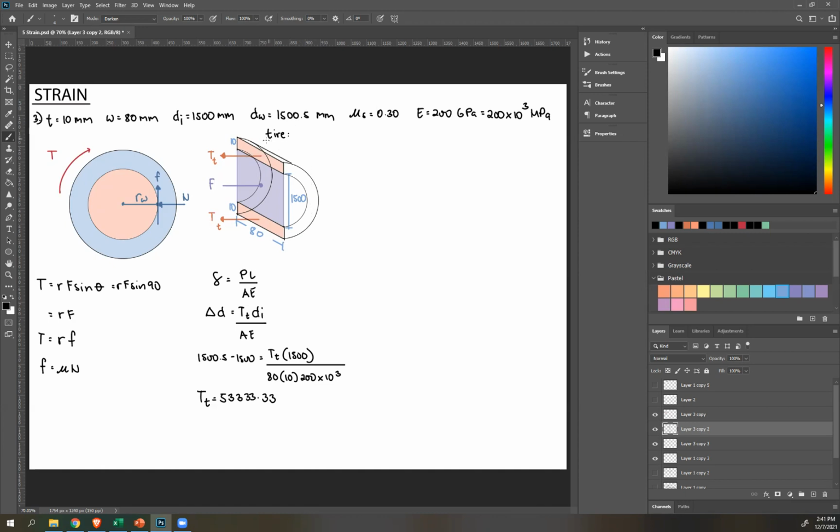I can use equilibrium equation here. Summation of forces equals 0, F to the right. Oh, this is Newton, by the way, because MPa. So F to the right, positive, minus, there's 2T over here. So minus twice T sub P equals 0, therefore F equals twice T sub P. Now recall this F is due to pressure, right?